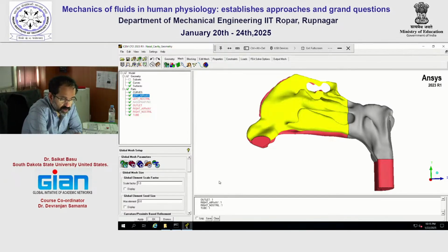Now, the gold standard, or I would not say the gold standard, but things that we have done mesh grid refinement studies on showed us that for a geometry like this, in the sense that a geometry that is ending at the base of the nasopharynx, and this bottom red region is just that tubular outlet which we keep to make sure that the flow is still well developed and we don't have any end layer effect at the nasopharynx. So for a geometry which is basically limited at the nasopharyngeal base, we saw that 4 million tetrahedral mesh elements is sufficient.